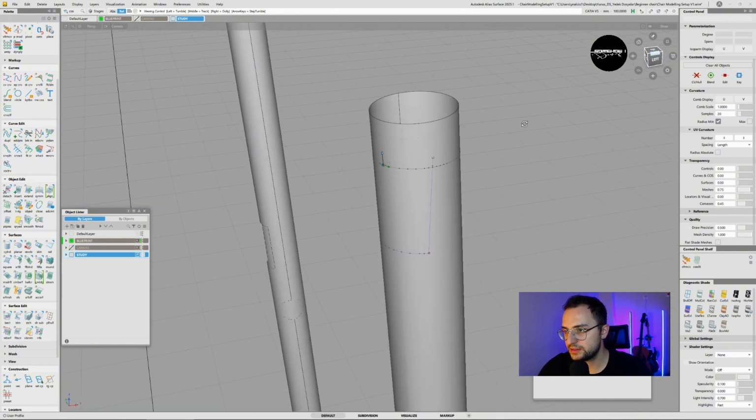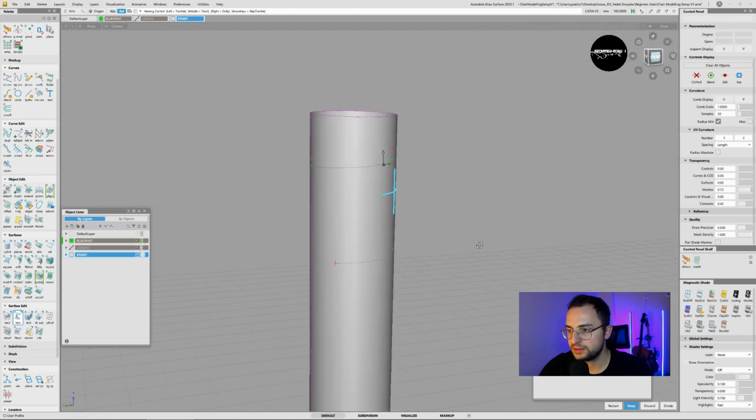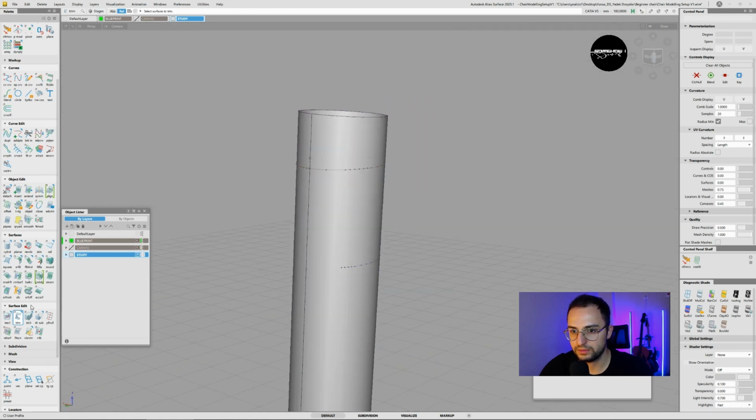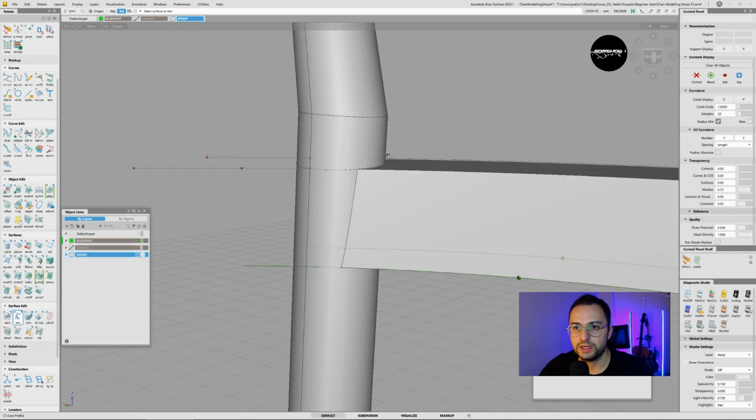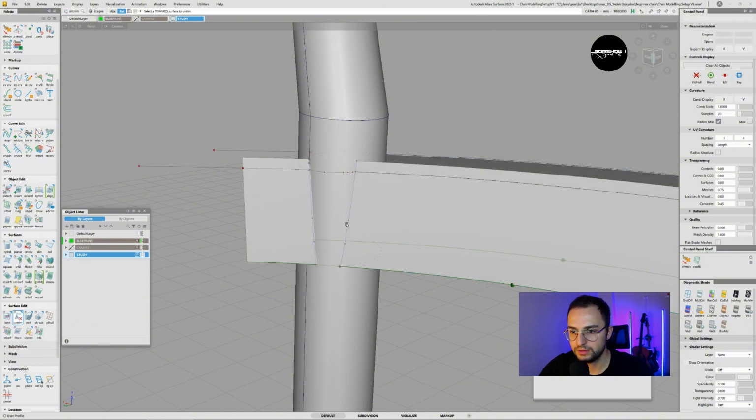And since this is rotating all around, I'm gonna select this area. Oh, we've done something wrong. We've deleted one curve on surface that was supposed to be there. Let's make it visible. Now we're gonna untrim this one, pick curve on surface, delete, intersect with this, that.